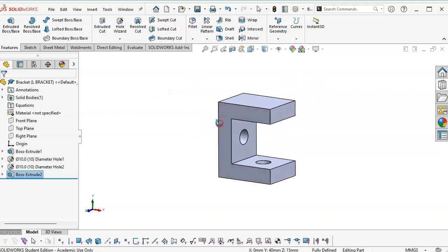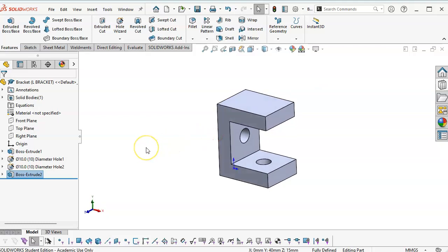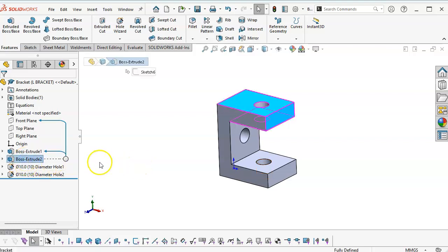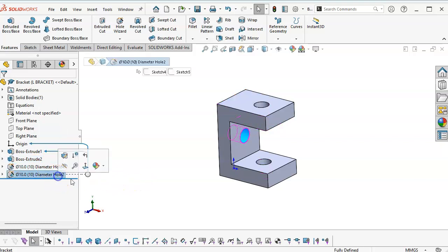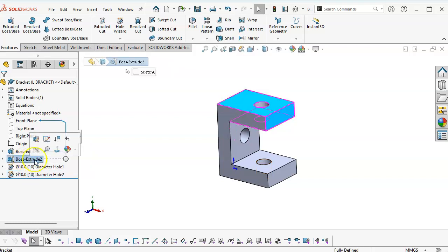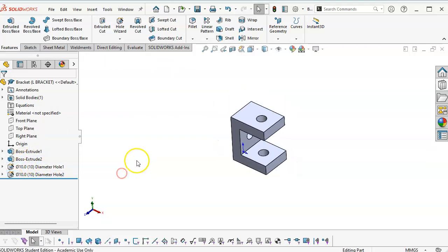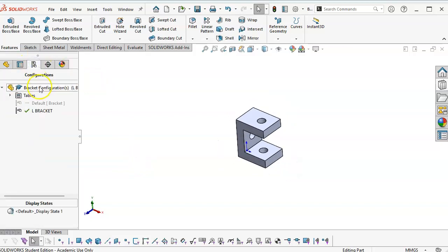So this is where we do the test and how we modify the geometry. All right, so at this point, I would want to reorder these. If I set up a condition where these little lines, all right, so my parent child, that is parent, I cannot put boss extrude 2 before boss extrude 1. But when I look at these, they're not tied to anything below. So there are no child features, meaning that this did not have any real implications for its geometry.